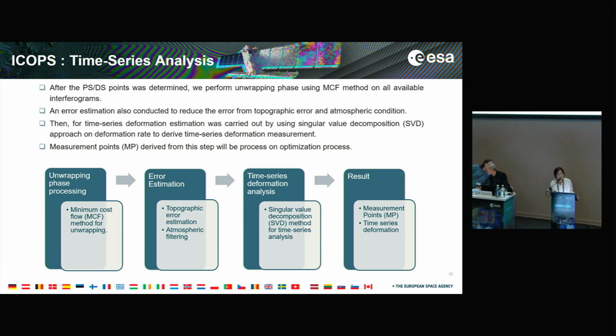An error estimation was also conducted to reduce the error from topographic error and atmospheric conditions. Then the time series deformation estimation was carried out using the SVD approach on the deformation rate to derive the time series deformation measurement. The MPD derived from this step will be processed in the optimization process.